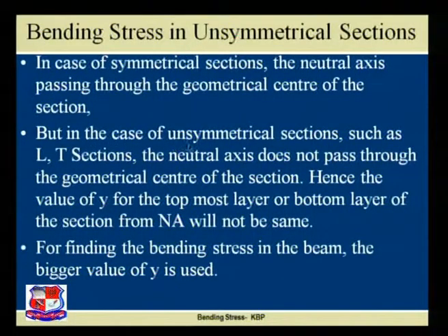But in the case of the unsymmetrical section, such as L section, T section, some specific I unsymmetrical section, the neutral axis does not pass through the geometrical center of the section. Hence, the value of Y for the topmost layer or bottom layer of the section from the neutral axis will not be the same. Hence, the first step is to find out this depth Y, either from the top or the bottom. Let us understand this on this tabletop.